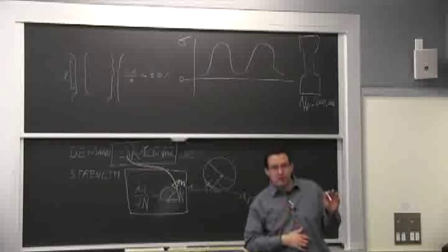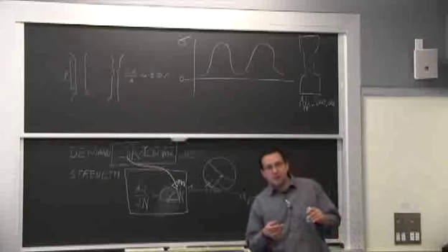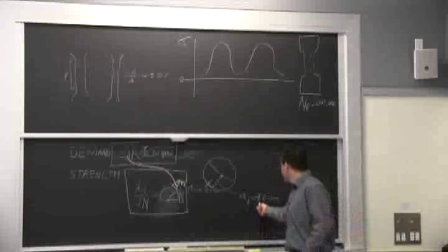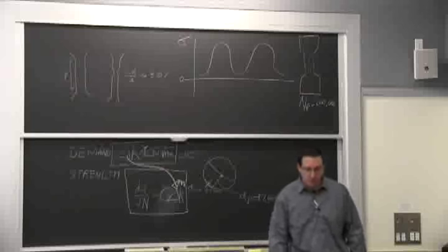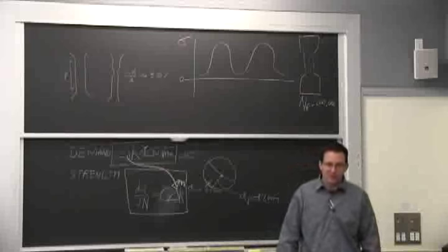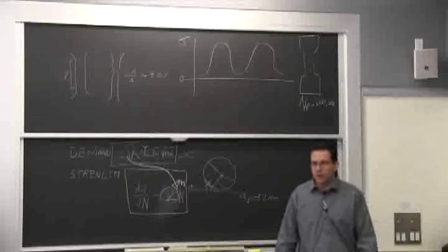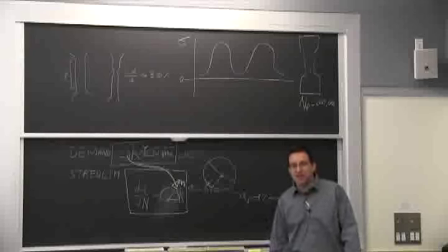If we don't know the stress level, so that would be sigma in this equation, but we know the fracture toughness, and we know the final crack length, say right here, it's a one-step equation to know what the stress is. Fatigue is not really even involved at this point. It's a one-step shot to have a good idea of bending stress for this geometry. So it's very powerful. It's never 100% precise, but it's definitely the best we've got.